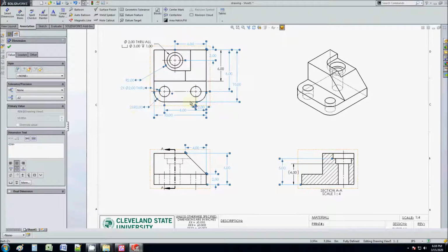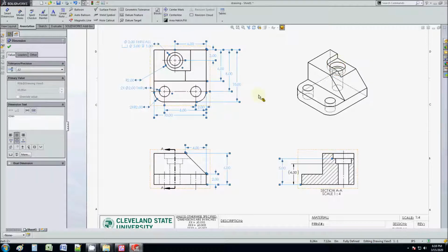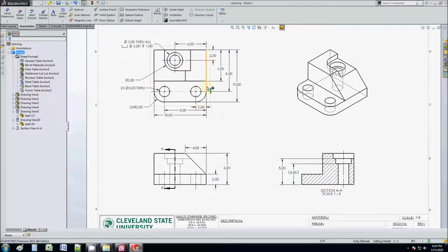We also know the fillet on the outside to cut the round. We also know where to cut this and how low. And then finally we need to know the details of the counterbore. So it looks like I don't have any missing dimensions. The only duplicate dimension I have is this. I never needed to tap onto it. But again, because it is referenced, then we're in good shape.